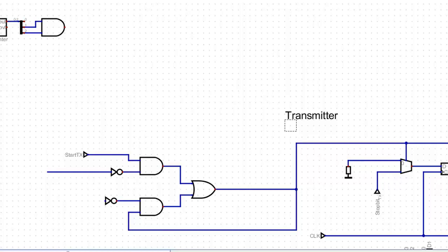Okay, what is still needed here? So this is going to clear the clock. So your clock enable. Yes. No, stop, don't do that. You've got a clock enable that you've connected to 5 volts. This means your counter will keep on counting all the time. Is that what you want?